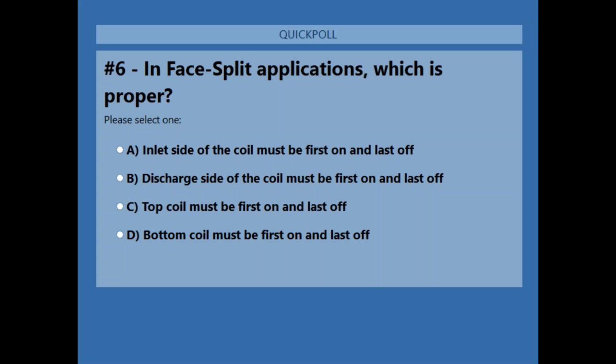Lance asks, does a standard commercial split system have all 3 types of lines, suction, discharge, liquid? Well, yes. Any system will have all 3, but a condensing unit with compressors in it will have a liquid line connection you have to install in the field, and a suction connection where you have to install the suction line in the field. There is discharge piping, but the discharge piping is internal to the unit itself.